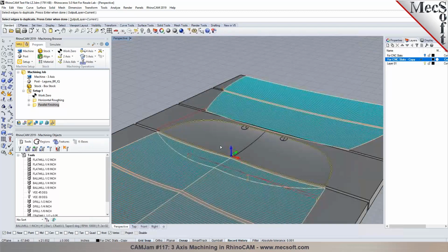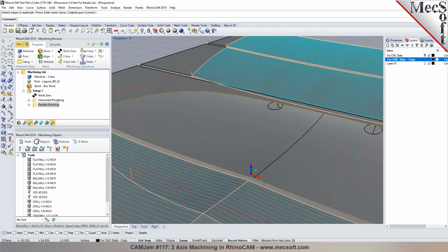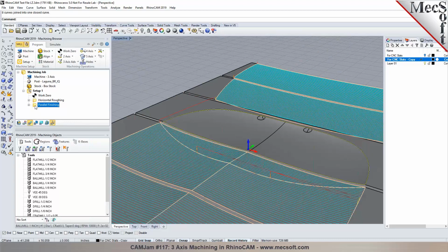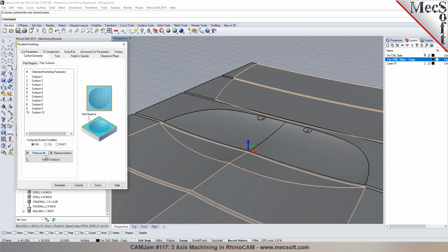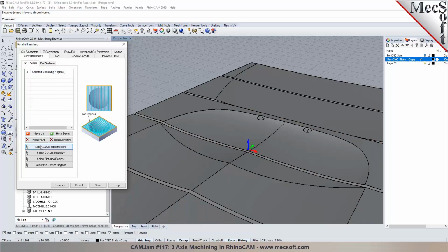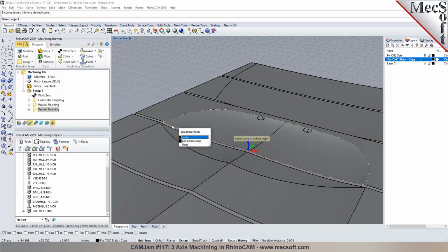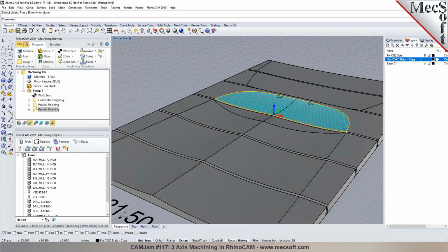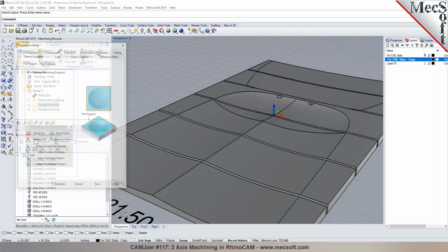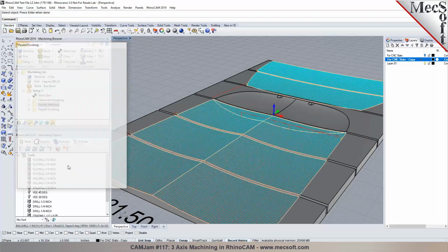And the problem might not be your boundary edge, it is that the surface has construction issues. Okay, I can go back in here. I just made a copy of the operation, and I can have this on a separate operation. But when you post, it'll all still be one file. So I could go back in here and also apply some sorting rules right there.